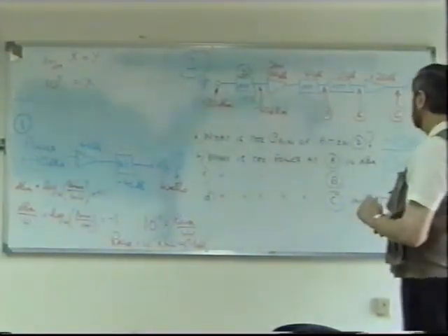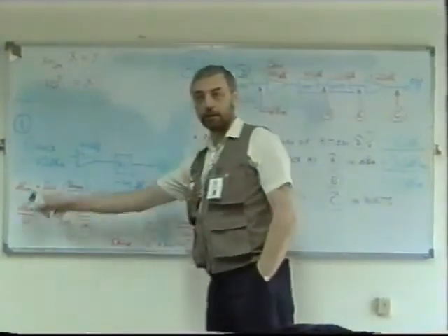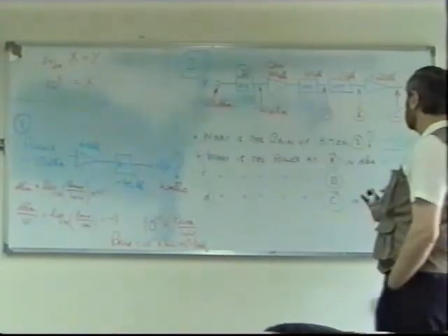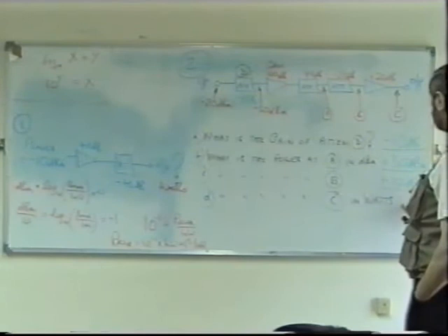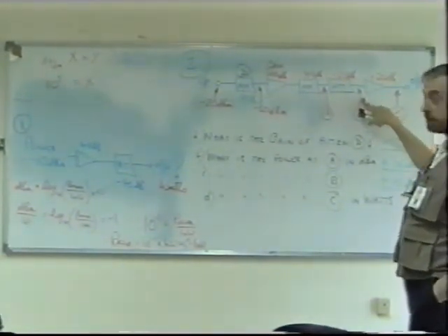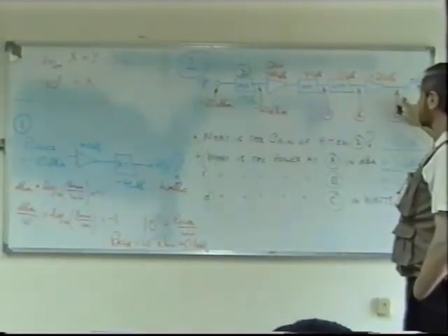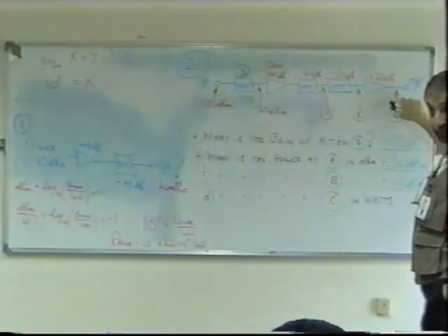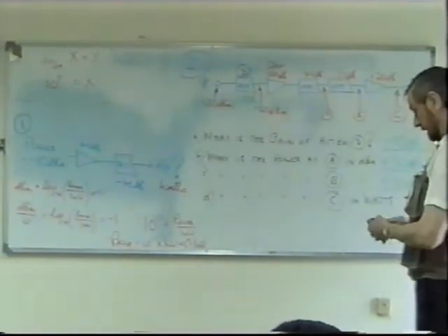Okay, now we want the answer at C. This is becoming a little bit like question 1 now, because we want the answer in watts or milliwatts or microwatts, whatever it is, or even kilowatts. We know the B is 10 dBm. The gain is 20. So what's C in dBm? 30 dBm. That's right. 30 dBm is the power at C.